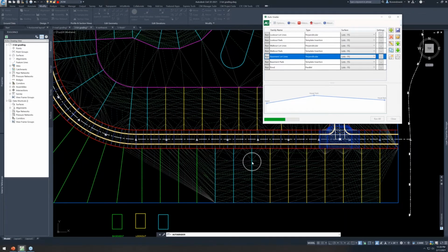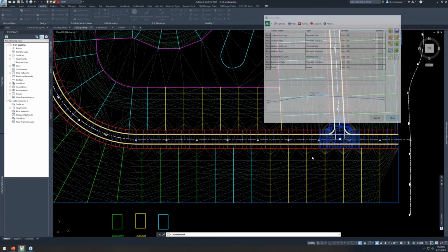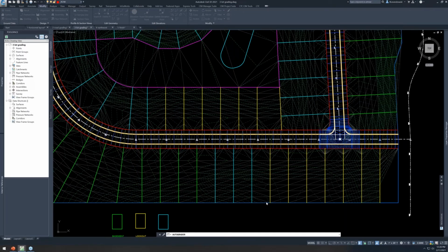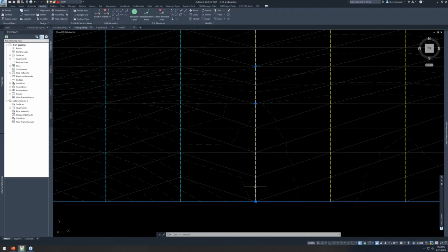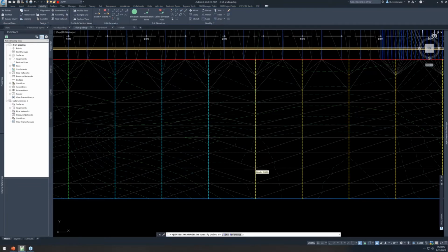Now I'm inserting grade break points along these lot lines, and because I only inserted a little ways down the lot line, what's happening with the back of the lot lines here? Let's take a look at that before we move on. Okay, I've got an existing property line out here, and that has elevations pulled from existing ground, okay? Now these lot lines are intersecting that. They're terminating right there. That's how I drew them. And so the slopes of these feature lines will vary depending on that back lot. So that's a slope of 1.08% there. I get 8.21, so on and so forth, okay?